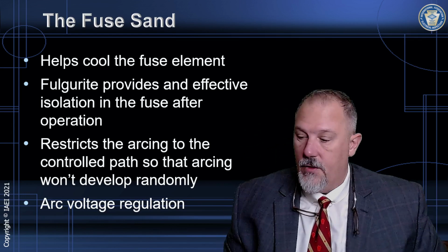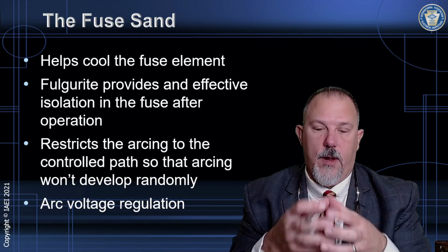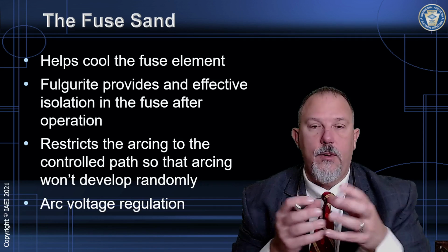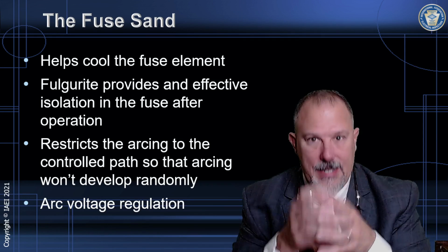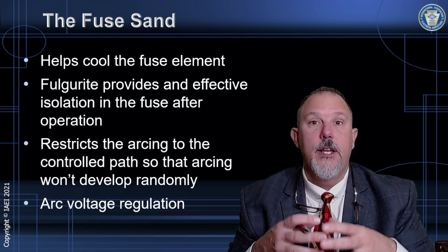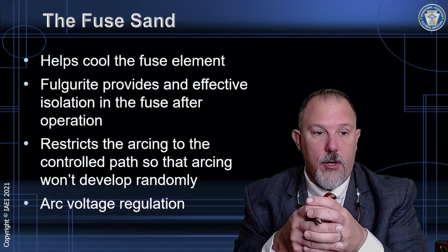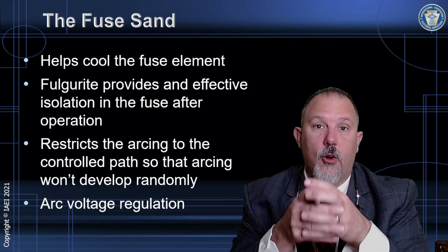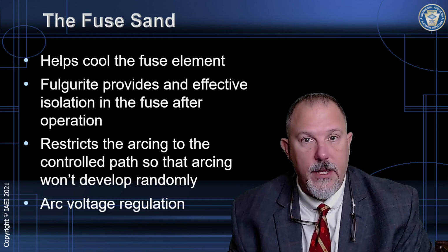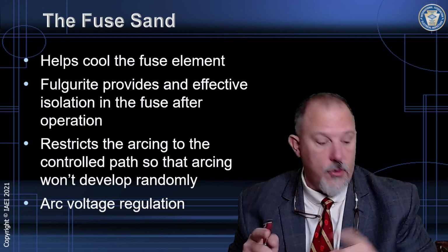So each one of those pinch points, when you have the sand around that element and it opens, will help contain that arc because sand is an insulating material. It will help contain the arc and restrict it around the element itself. And that way it helps regulate the arc voltage, which is the voltage across the arc when you draw an arc.